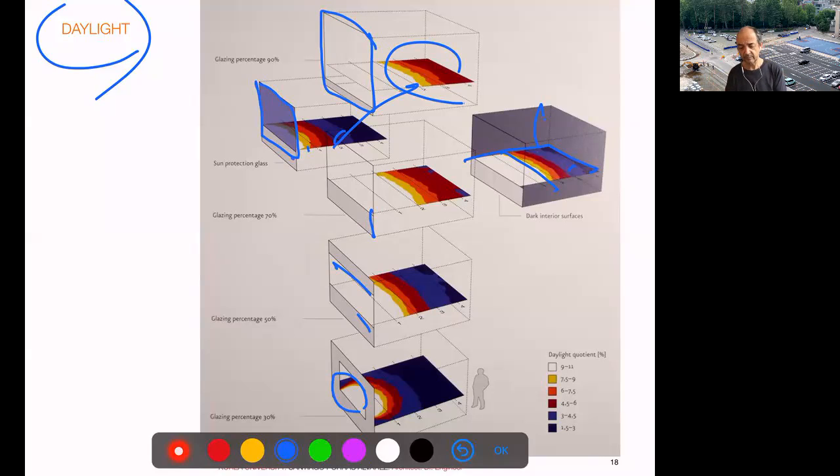Usually, remember, as a rule of thumb, if this is the height of the window, we consider we have acceptable light up to twice that height. This is why for the usual 2.5 to 3 meter ceiling, we think of rooms of 5 to 6 meters depth as having nice natural light. They don't need more. You may have experience with classrooms in which next to the window you're happy, in the central rows you're okay, but if you're on the opposite side, you will always depend on artificial light to have a nice light level.